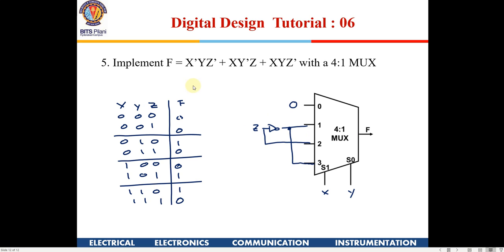Yeah, because without the truth table, again it is simple. You can apply 0 0 here. Once you apply 0 0 here, you will find that it is all zeros. For the case of 0 1, if you apply 0 1 here, what happens? z we have to keep as it is. If you keep 0 1, this vanishes and z dash will remain here. Here also this will vanish, but only z dash will be available here. So you put z dash. Accordingly we will get the output in terms of z.